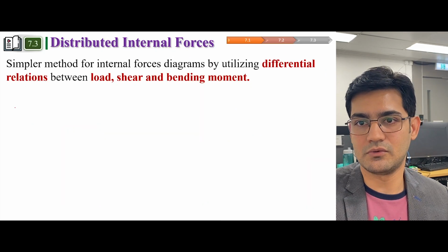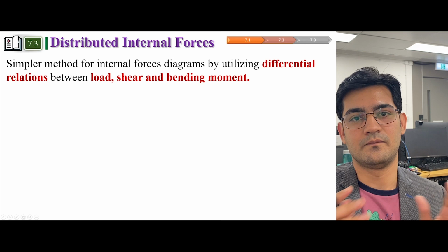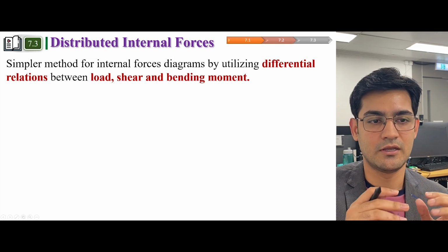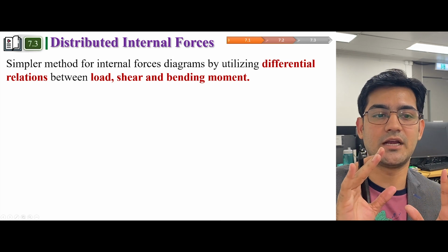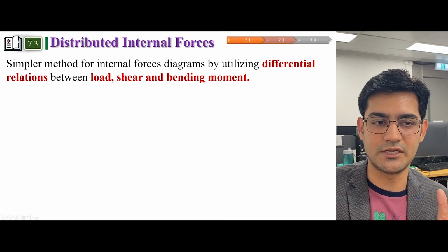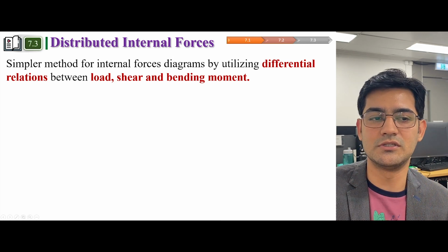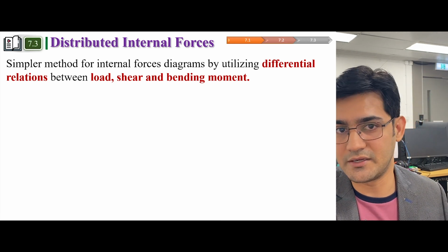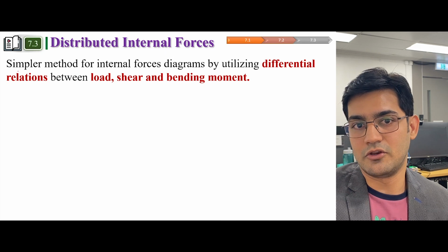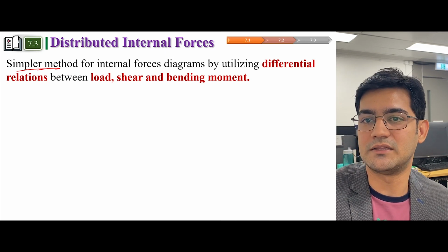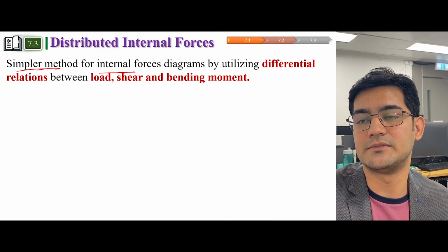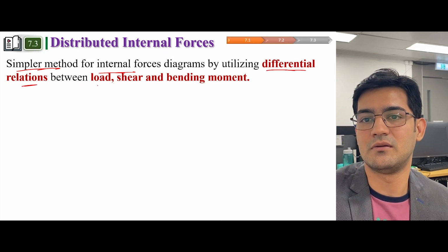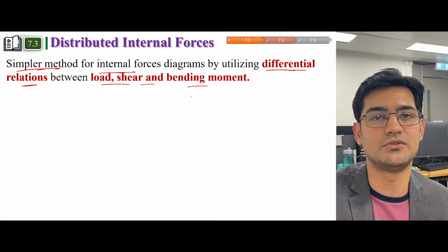Okay, so sometimes this method also gets complicated, because imagine if a beam is subjected to several concentrated forces, couple moments, and distributed loads, then this method of constructing shear force and bending moment diagrams becomes quite tedious. So in order to solve this, we have simpler methods to calculate internal force diagrams, and we can utilize differential relations between load, shear, and bending moments to draw this.